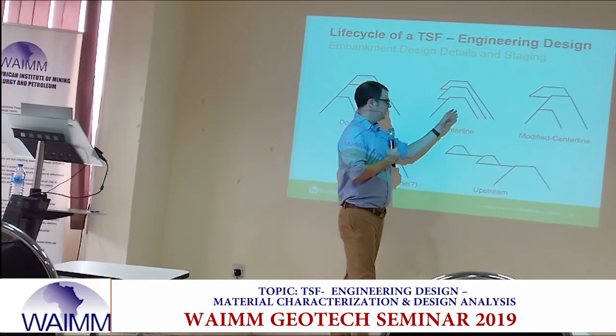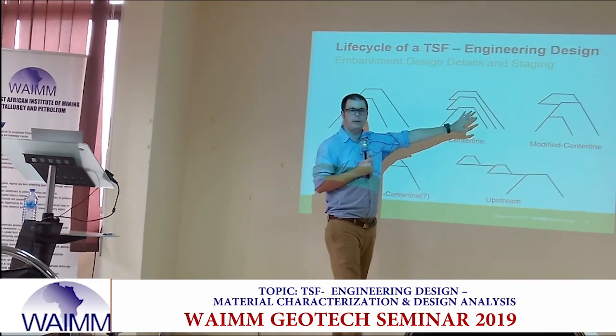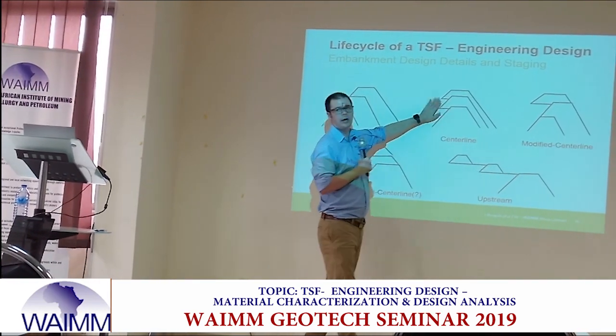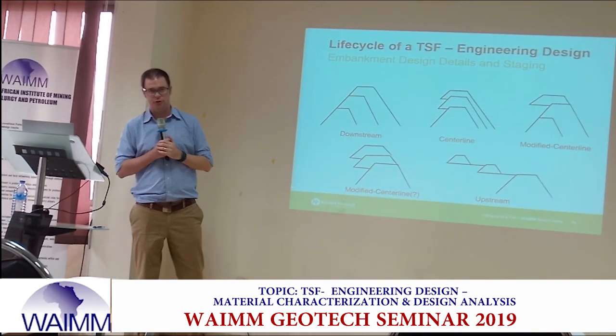The benefit here is that, compared to this, we reduce our fill volume somewhat, but now we start relying on the strength of the tailings. And so we need to make sure that we properly accounted for that strength.